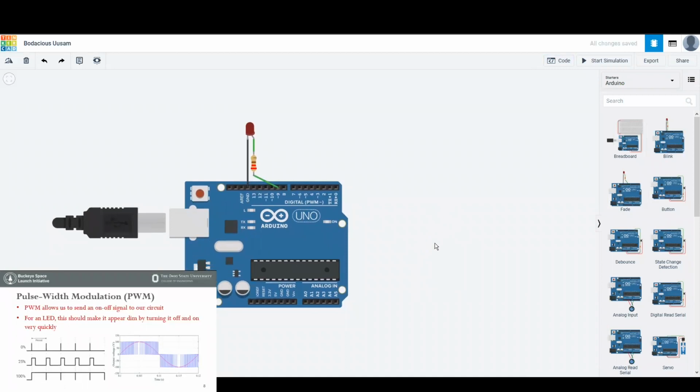While we're here, I want to talk a little bit about using the Arduino as a battery, and how before in the example we went through Ohm's law to determine the resistance value. Notice that we had 50 ohms for 3 volts. Now we have 220 ohms for the Arduino. Real quick, this corresponds to a 5-volt output voltage from these pins.